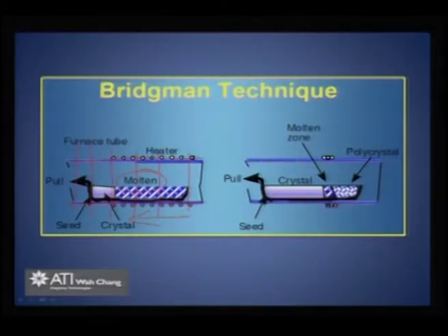Therefore you need to keep this area at one temperature, and this one at another temperature, and this one at another. So you need a very gradual temperature gradient like this, so that as you come out you will be able to grow a defect free crystal. Suppose you just pull it out, which you call quenching, then there will be a lot of imperfections in the crystal that is grown, because definitely it will solidify when you pull a melt, but that is not the way you grow a crystal.